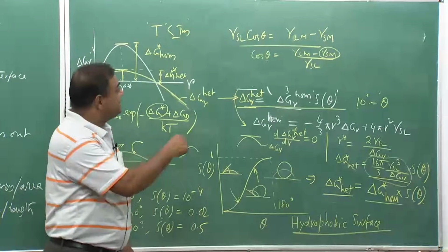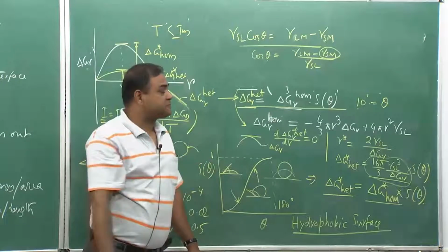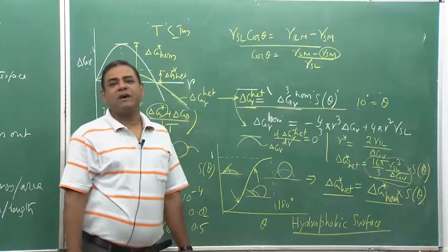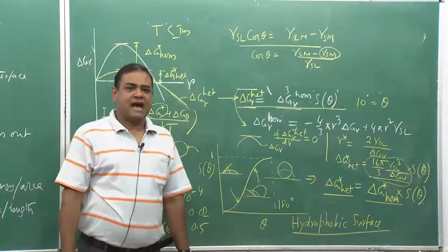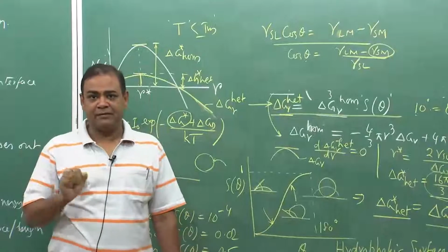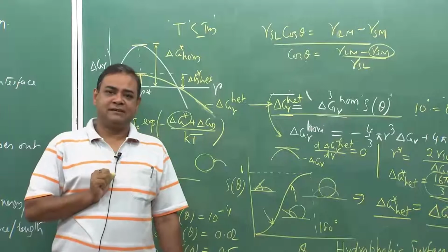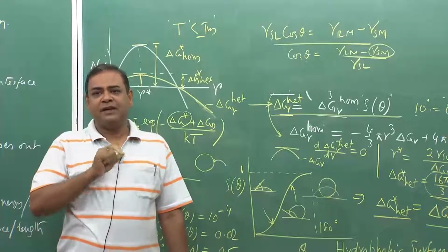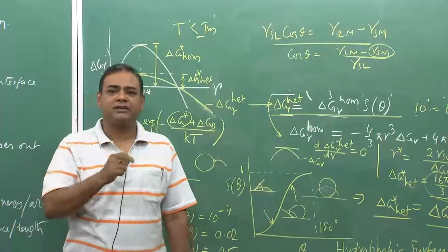Okay. Now, what is its application? Now, we are thinking from the expression point of view. The application is inoculation. You might have come across this word, inoculants, and in the casting process many times we add inoculants in the metal, and those inoculants act as nucleating sites. On the surface of the inoculant, the liquid wets that surface and the solid starts forming on that inoculant.